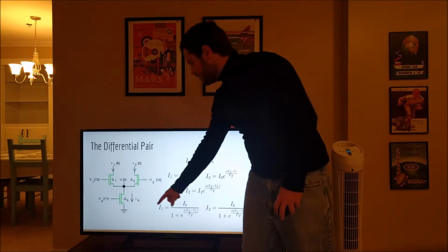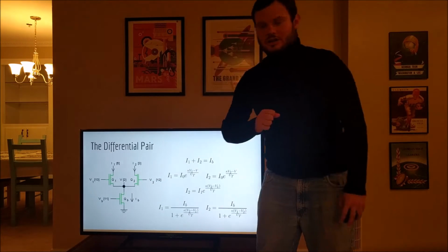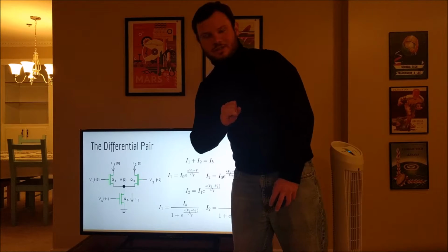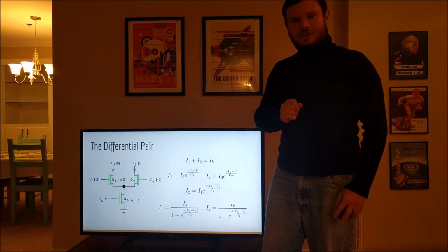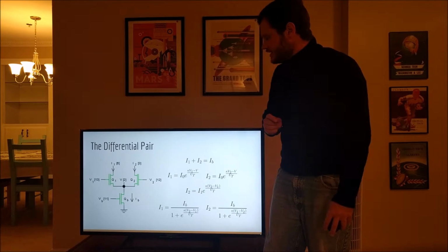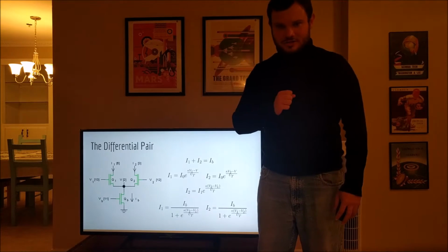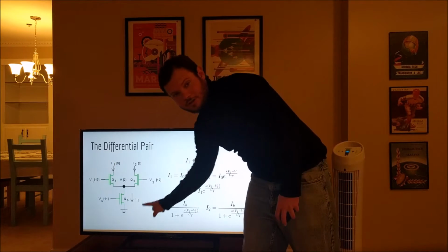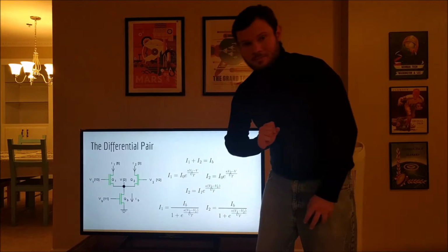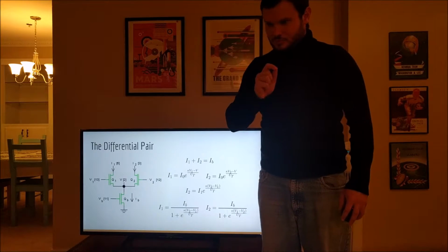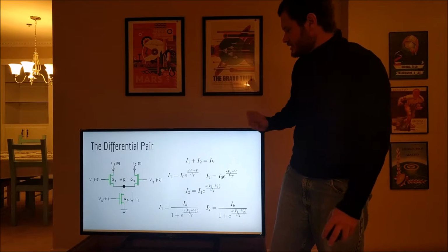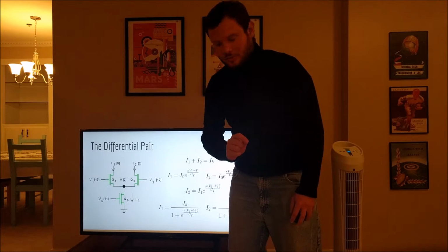It is assumed that the biasing transistor here is subthreshold, so the current through both of these must be subthreshold as well. To derive the currents, we use KCL and the IV characteristics of these subthreshold transistors. There's only one free parameter in the system, the drain voltage here, so we can determine I2 in terms of I1 to eliminate this free parameter.